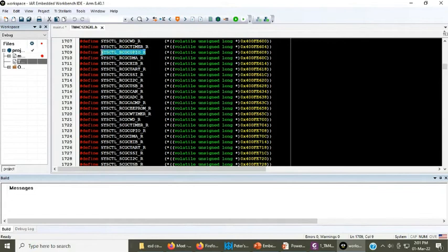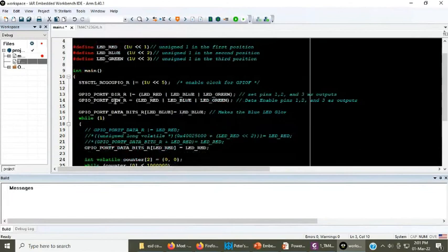So use this particular register, copy, paste it here, and because we have to make the 5th bit position 1 to activate the clock in the port F, this is the command. By this command, you are entering 1 in the fifth position or R5 position. Okay, bit position 5. Then we used a different command to reach the dir register.